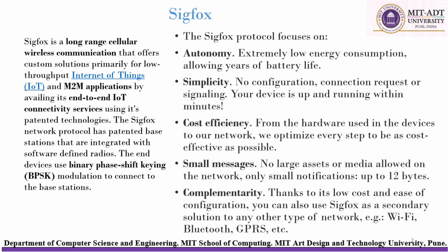Next important thing about the SigFOX protocol is that it focuses on small messages. It doesn't require large assets or media, which are not required at all on the network. Very small messages are sent, up to a size of 12 bytes, only small notifications.